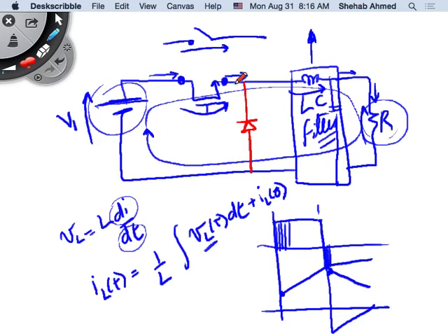What will that do to this scenario that we just described? Remember what happened: because we opened this switch, this inductor voltage went shooting through the roof because the current is continuous. So this switch would see crazy, very high voltages across it, and these arcs that we just saw would always be appearing. So this thing will be glowing, right? This is not what we want to do in power electronics. So we had to find a solution.